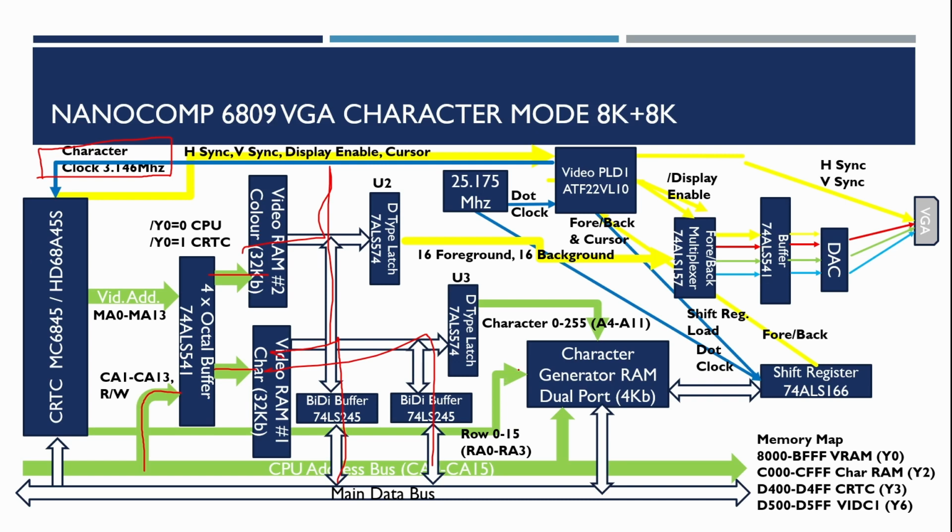and what this does is allow the character generator ROM, or RAM in this particular case, which means the characters can be software definable. What this does is output from the chosen character an 8-bit value that chooses address lines 4 to 11 on the character generator RAM, but then the bottom A0 to A3 are chosen by the row of the current character that's selected. So what this means is that as the character is drawn, it does each individual line of dots for the character.